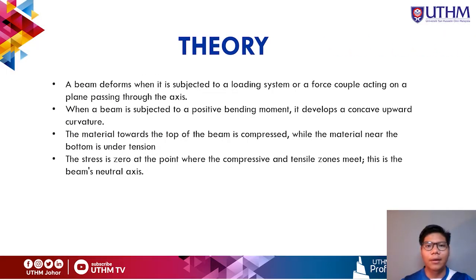My name is Muhammad Zaibin Baharudin, metric number AD100167, and today I present the theory of this experiment. First, a beam deforms when it is subjected to a loading system or a force couple acting on a plane passing through the axis. Next, when a beam is subjected to a positive bending moment, it develops a concave upward curvature. The material towards the top of the beam is compressed, while the material near the bottom is under tension. The stress is zero at the point where the compressive and tensile zones meet. This is the beam's neutral axis.